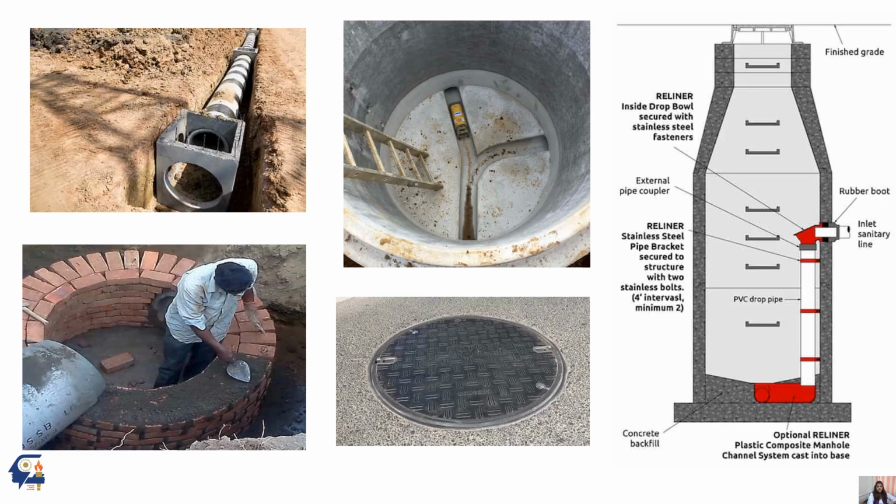So first one is excavation. Next, we have benching being done. Then we have laying of the bricks. Then you can see the cover. So you can see on the right side, this is how the finished manhole would look.